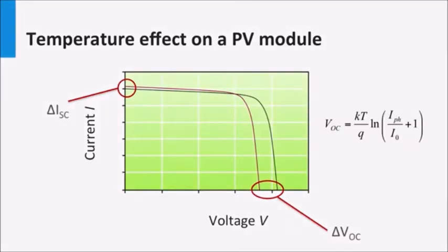The decreasing effect on voltage can be explained from this form of the basic diode equation seen in the earlier weeks. While the temperature affects the various terms in the equation, the net effect of temperature is that it decreases the open circuit voltage linearly. The drop in open circuit voltage with temperature is mainly related to the increase in the leakage currents of the photodiode, I0, in the dark with temperature. The I0 strongly depends on the temperature. We have dedicated one of the exercises this week to this effect.